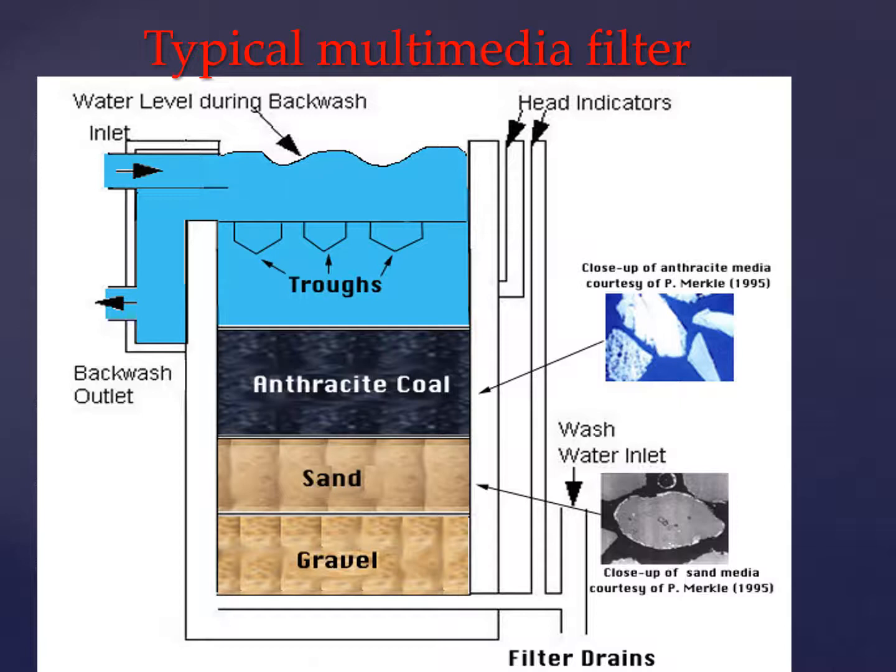Let's see what happens in the filter. If you see here at the top left, you see the inlet, water enters, and you filter water from the top to bottom, and then you collect treated water from the bottom of the tank. But after 24 hours, depending on the filter and the quality of the water, you backwash it. When you backwash it, you take water from the top in troughs.